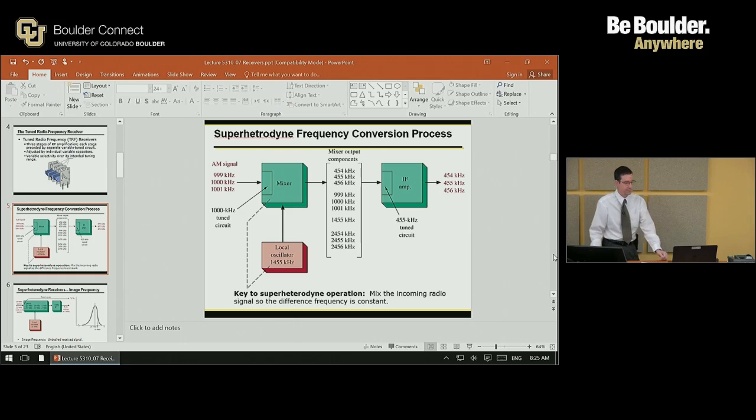For the... oscillator should be reduced or increased by 1 hertz, so the other nodes will not be increased, isn't it? I didn't quite catch that question. The local oscillator now is 1455. Right. Plus the 999, or minus the 999. Right, so you've got these 2. Yeah, I believe, as per my understanding, that the local oscillator should be increased now.